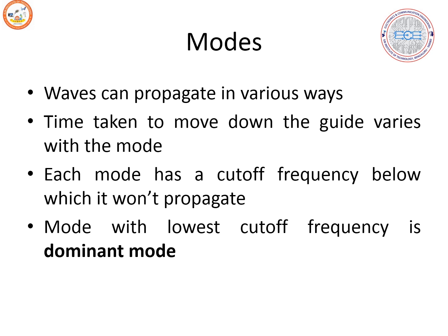So the time taken to move down the guide varies with respect to this mode, and each mode will have a cutoff frequency. Below that cutoff frequency, the signal will not be allowed to propagate. So we specify the mode with the lowest cutoff frequency as the dominant mode.